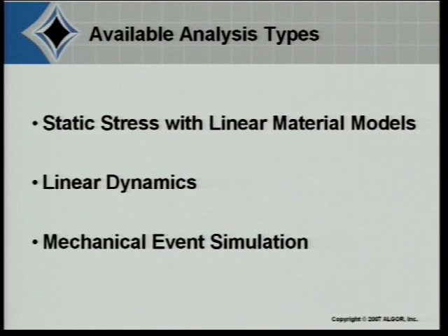The analysis types available for composite elements are static stress with linear material models, and linear dynamics, and by those we mean the natural frequency analyses and other vibration analyses such as random vibrations, frequency response, response spectrum, and so on. All these fall under the linear dynamics analysis types, and they have composite elements available for use in them.